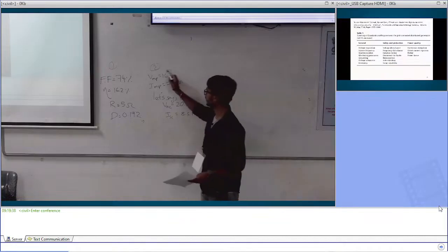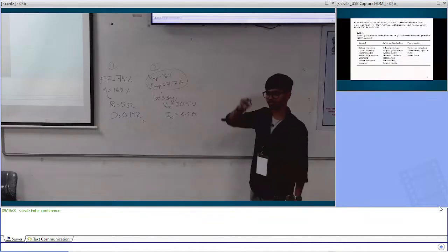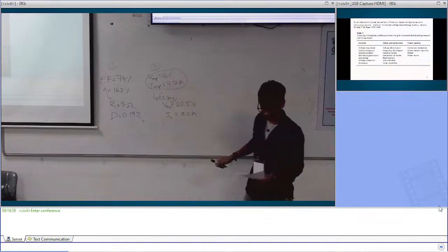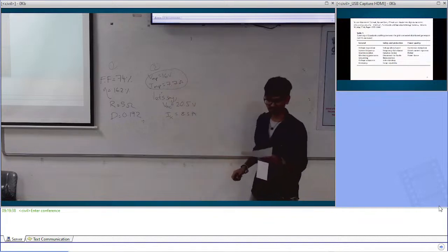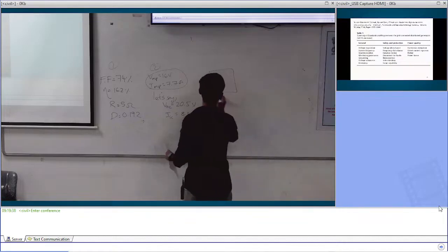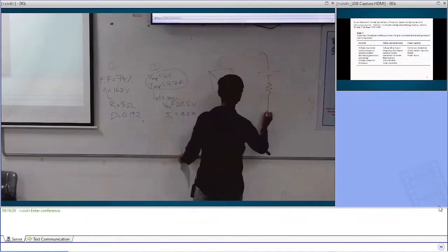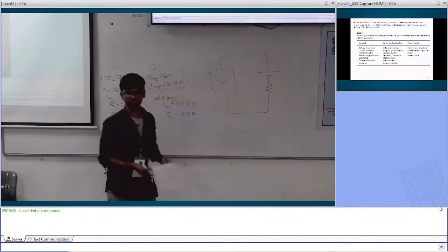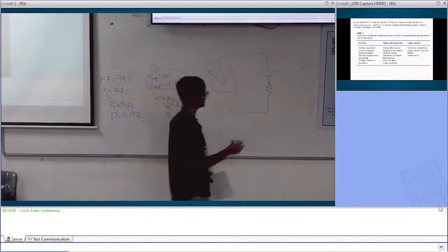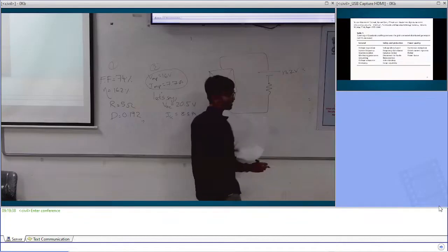So we have taken VMP and IMP as approximate values. So you can take the values that we have got from the plot. We have taken nearest values. So the next part of the question, when battery is connected across the panel, we have told that a battery is connected across the PV panel with open circuit voltage as 13.2 volts and internal resistance as 1 ohm.